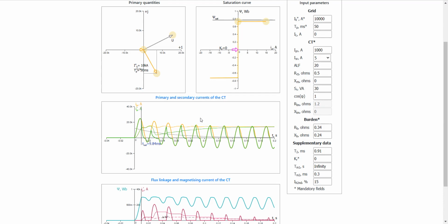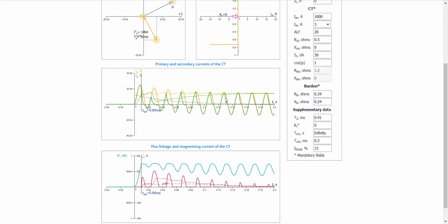I should also say a few words about the integral current values, which are represented in this plot by these slim lines. These are the amplitude values of the fundamental frequency, which were obtained applying a DFT filter over a full period window. For the model, we've chosen the amplitude values instead of RMS values, so that it becomes more apparent how the integral lines gradually approach the amplitude values of the sinusoids, and how saturation becomes less and less important for the measured signal. DFT means discrete Fourier transform, by the way.